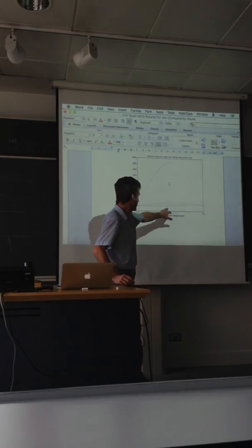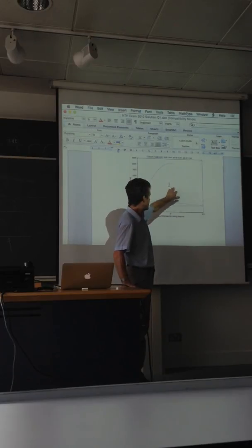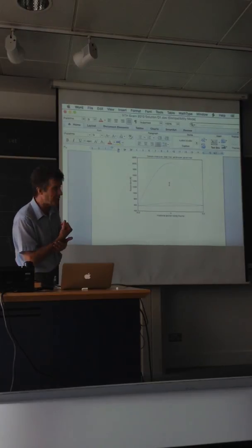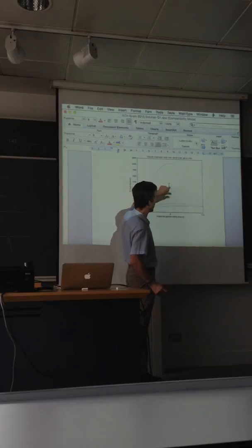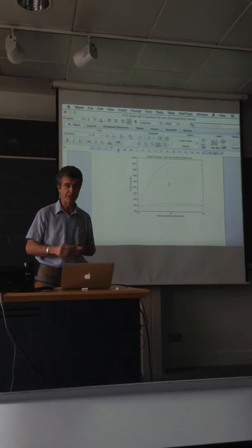That with the coolant, clad outer, clad inner, pellet outer, pellet centre. And just to get a sense of the relative size of those differences, of what this enormous delta T radially through the pellet is. That's this big parabolic profile where we started the morning discussing.